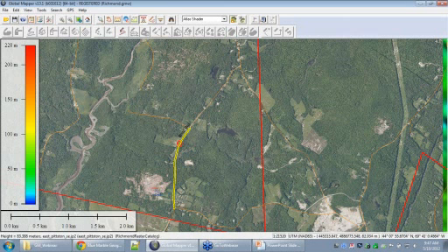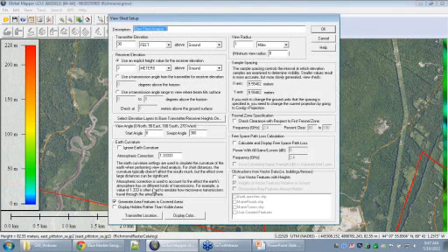So what I'll do here is I'm going to stick a tower on the top of our hill in this area that we've got some cleared out trees. And you'll see there's a number of options here for what we're going to be doing with this tower height. We can apply a transmitter elevation. So the transmitter is the tower that we're going to be locating at the center of that. If we want to do a visual line of sight here, maybe we're going to have a 30-foot tower on the top of that hill.